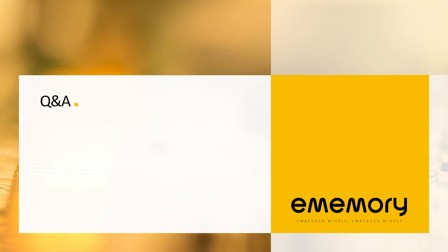Let me reply to some questions online for you. Someone asked one question: is it MTP, and how is the endurance level? Yes, it's MTP, and it's based on our digital memory developed into the multi-level memory. So the endurance can achieve maybe 10 to 100. But if you want a higher endurance level, maybe it can achieve 1K, 1,000, it should be okay.